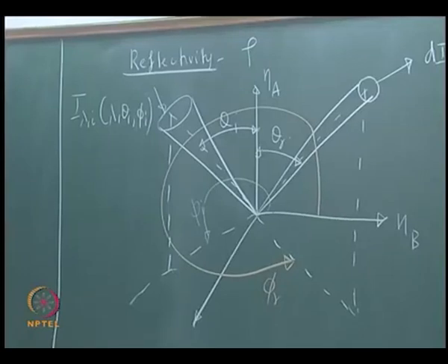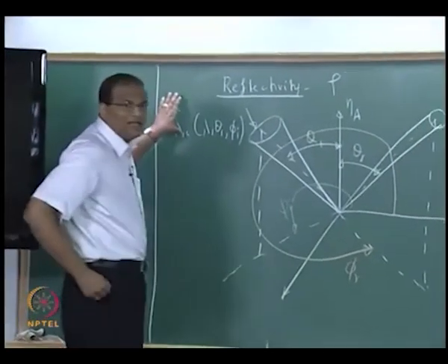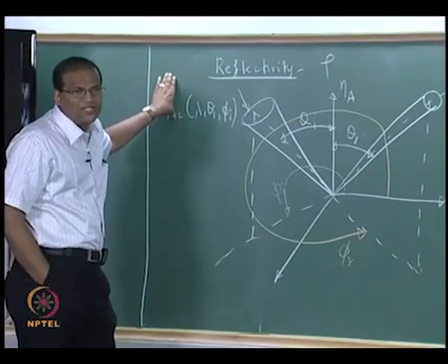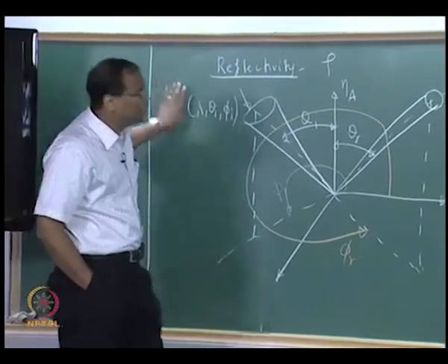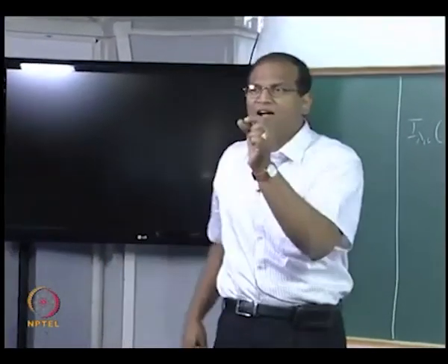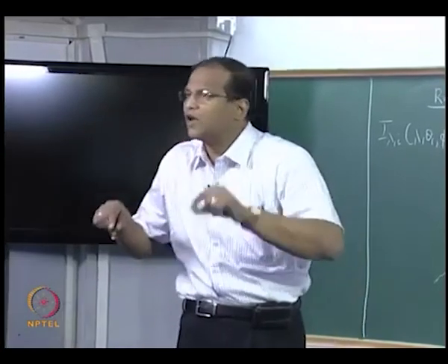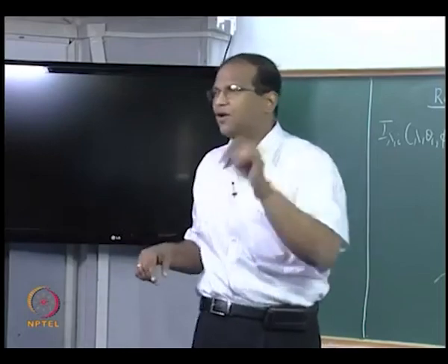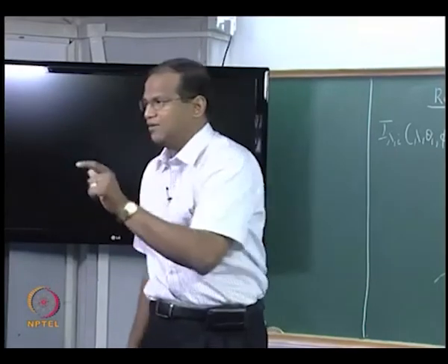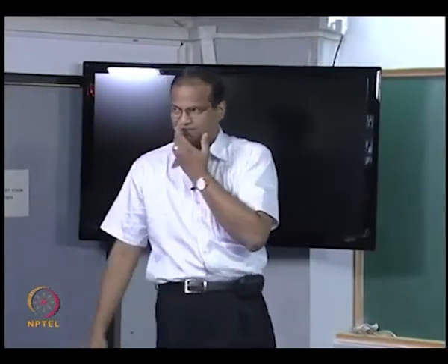So I lambda I is incident from a particular angle theta I phi I. The reflected can take place in any direction. We are looking at reflection from an angle theta r phi r. Now please note, as opposed to the absorptivity, there is a significant departure here, because for the reflected I am putting it as dI lambda r, because this theta r phi r is a small direction. There is a small solid angle in this big 360 degrees over the hemisphere. Therefore I expect the reflected component to be small as opposed to the incident. Therefore I call it dI lambda r. Is it okay?